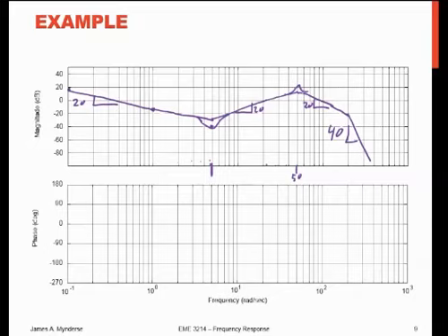The phase, I have minus 90. That continues over. My corner frequencies for that first 0 were at 42, somewhere about here, and it went 45 degrees. No, it's complex. There's two of them, so it goes a total of 90 degrees. So at 0 degrees at 5, and the other corner was there. The phase is going to go up like this,